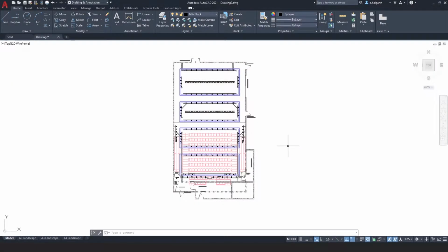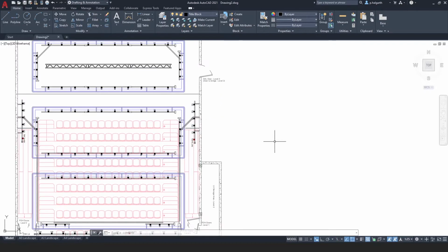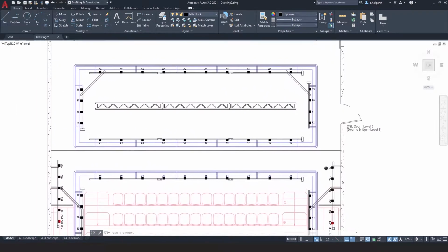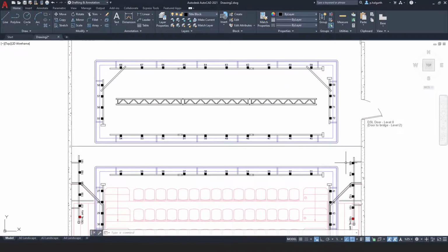Quite often when we're drawing in AutoCAD, we want to reference objects in relation to the coordinate system of 0,0. Now when we're drawing theatre plans, it is common to have the middle of our setting line as that reference point. And here you can see that I've got a very basic drawing of a studio theatre space, and we have some auditorium seating, and in front of that we have our front edge of stage, which I'm going to use as our setting line.